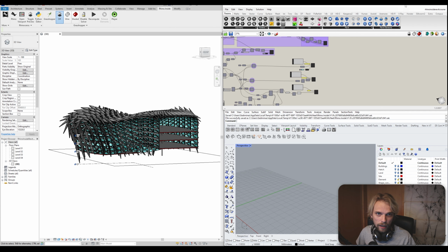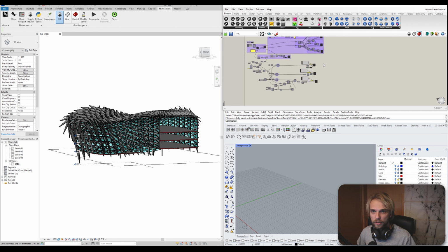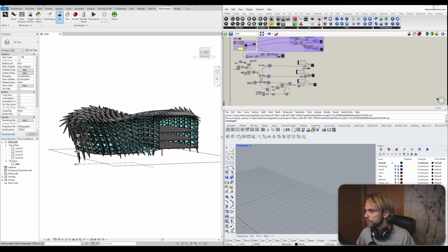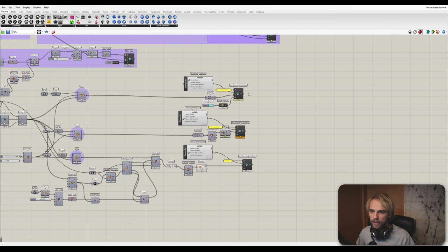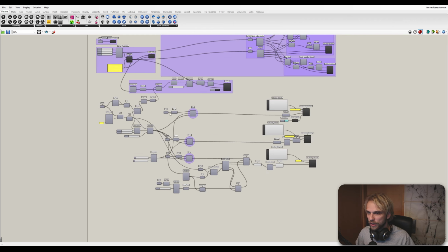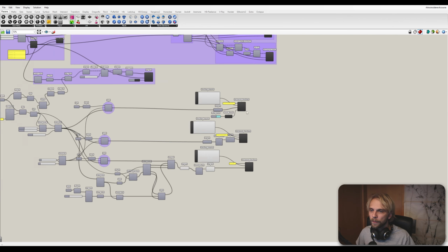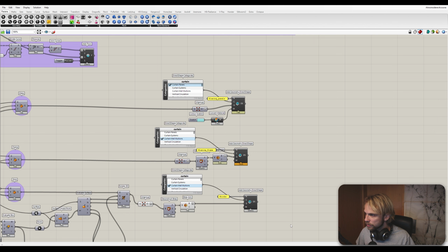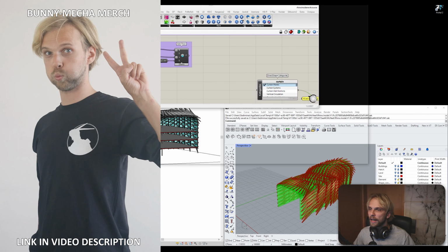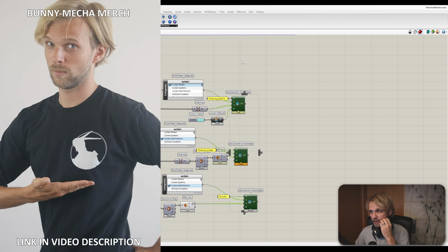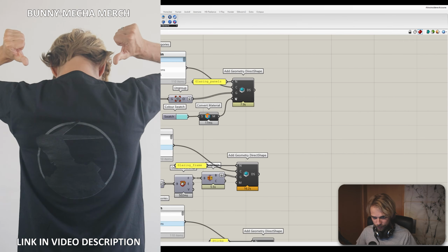First off, I have my Grasshopper script opened right here, and I want to do a few things with it. First thing being, right now it doesn't matter what I change on this side, it will always send the information or the panels, the facade. It's always going to be sending over the facade to Revit, and I don't want that because that is a very heavy thing to do.